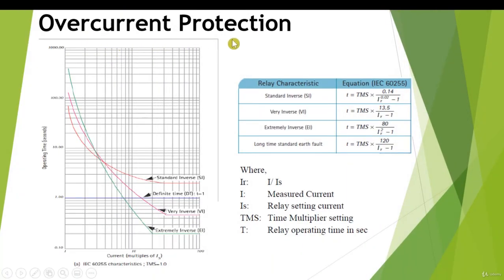In order to apply the overcurrent protection, you need to consider the proper relay characteristics such as standard inverse, very inverse, extremely inverse, or long time standard earth fault. And the equations of these characteristics are defined in IEC 60255 standard.